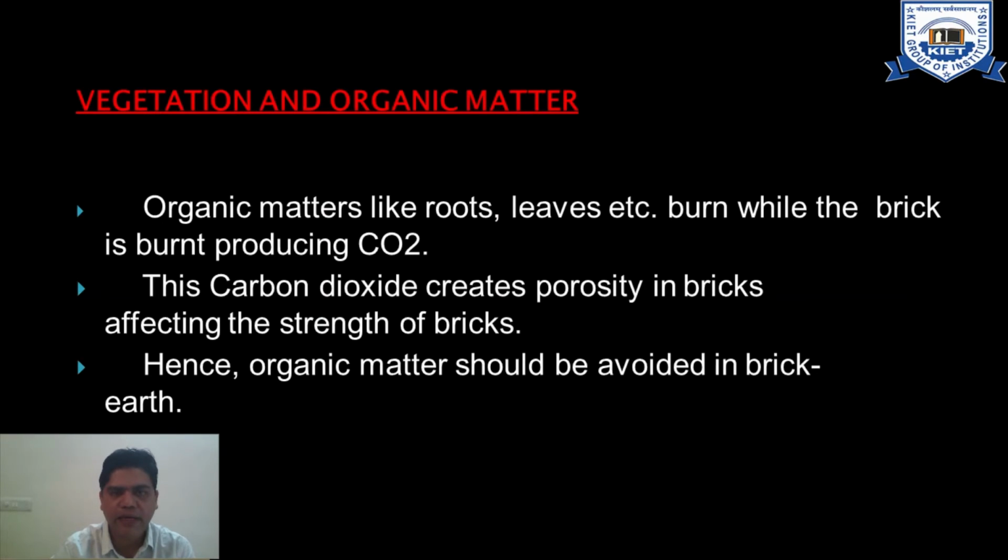The organic matters like roots, leaves, etc. burn during the burning of the brick and gas is produced. This carbon dioxide creates porosity in bricks, affecting the strength of bricks. Hence, organic matter should be avoided in brick earth.